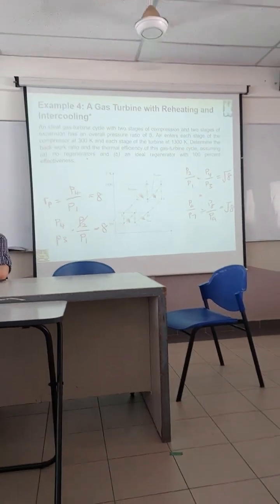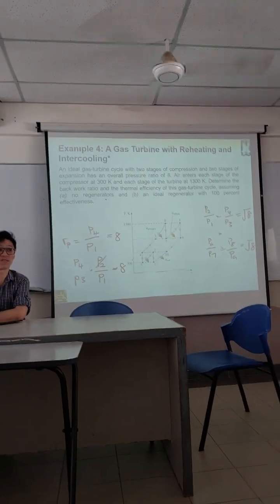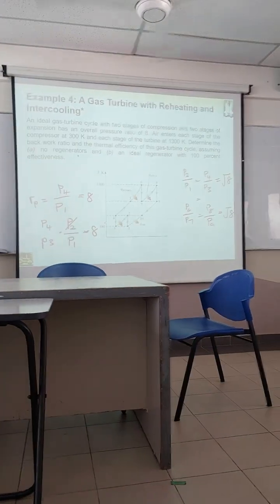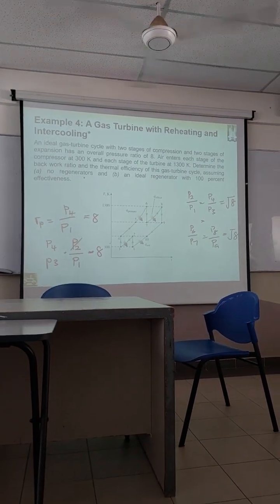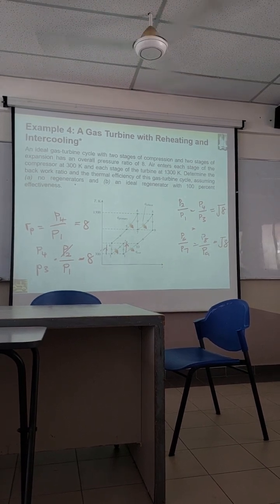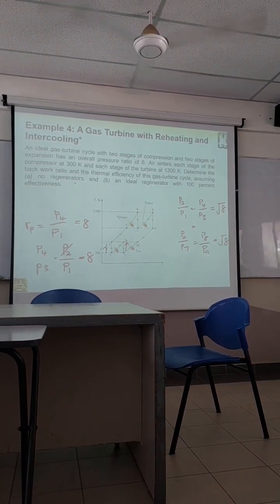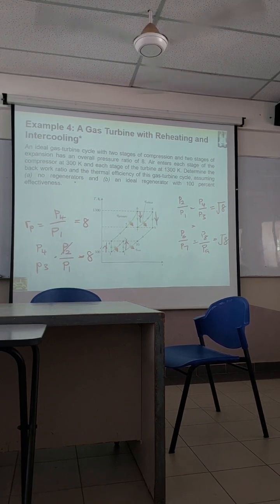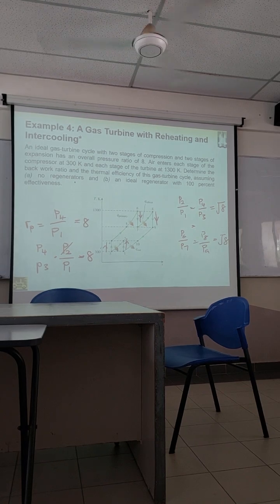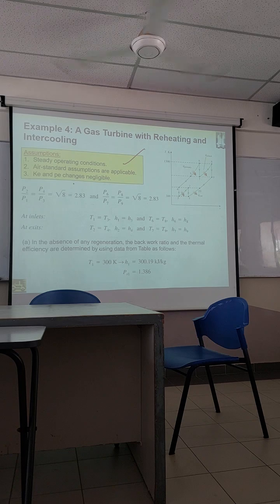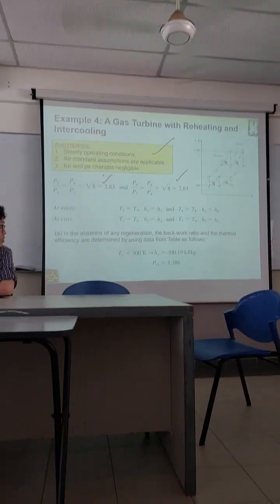It actually is the same way of doing as the previous methods, like the basic version. So from 1 to 2 is still just isentropic compression. 3 to 4 is just another round of isentropic compression. And here also isentropic expansion, which also indicates the assumption, this one don't forget. Now here we show you how to get the pressure ratio.